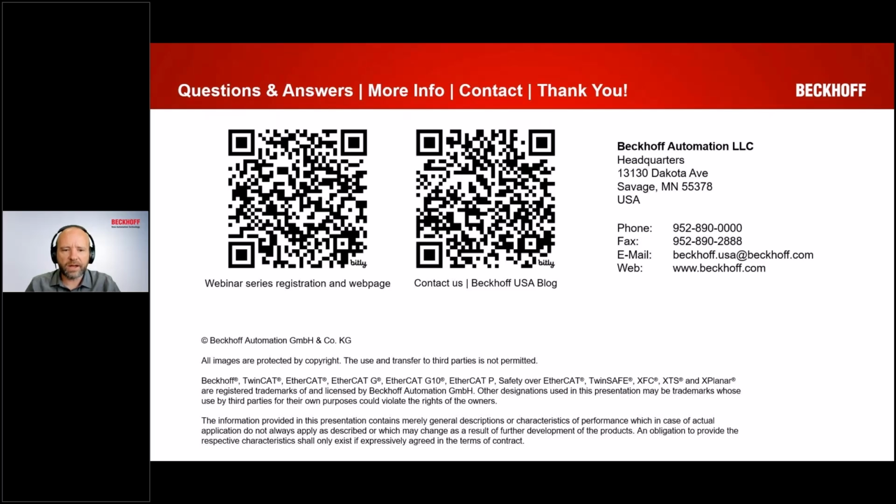Question about using the package manager with TwinCAT version 3 4022. Yes, absolutely, you can do remote manager for 4022. You would install the package manager with 4026, have all that, then you would install the remote manager from that outdated feed. There are a few versions for 4022. There are actually versions going all the way back to 4018 that I've seen, and in addition the TwinCAT 2 engineering. So there's quite a few options. So 4022 works there.